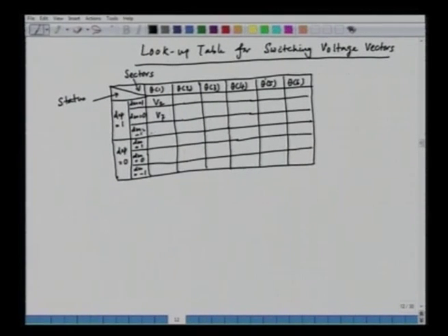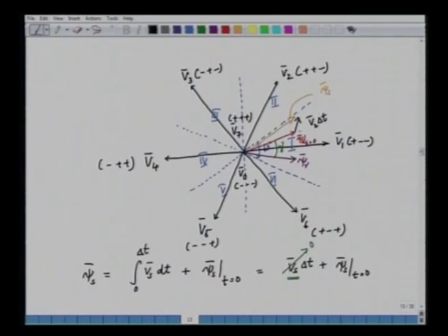And then the third row here, the flux d psi equal to 1 and dm equal to minus 1, means flux should be increased, torque should be decreased. Now, we have the flux vector in sector 1, and we have to increase the flux but decrease the torque. So, gamma has to be reduced. It means the flux vector should be decelerated, but the magnitude should be increased. So, we will apply such a voltage vector which will make gamma small.